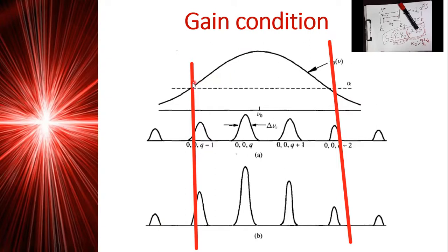And as you can see, even the amplification ratio is different. That's why the central frequency, or the central resonance, is amplified in a greater ratio with respect to those on the left and on the right, because it sees a higher amplification coefficient with respect to others. So you can manage to select which resonance you would like to amplify and which resonance you would like to decay or kill based on this management.